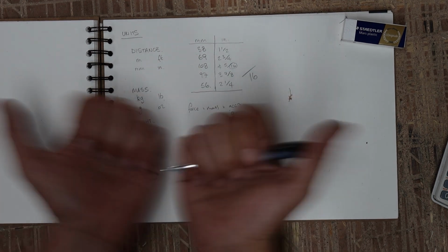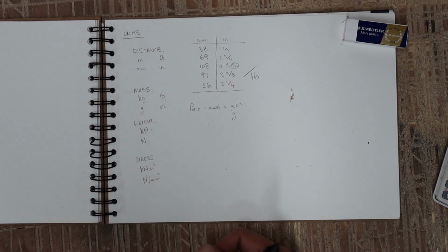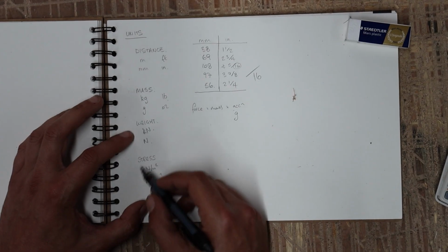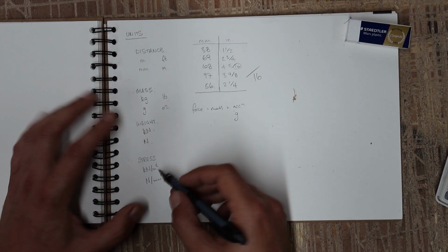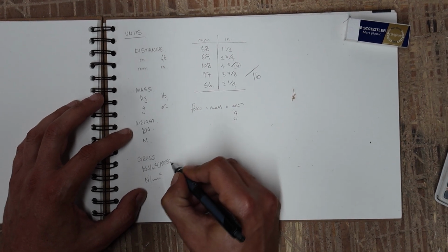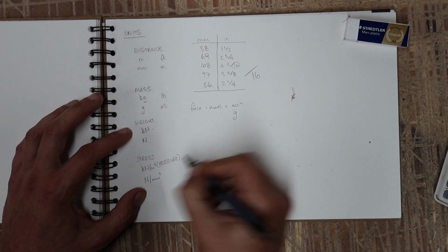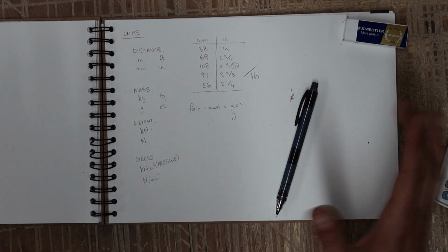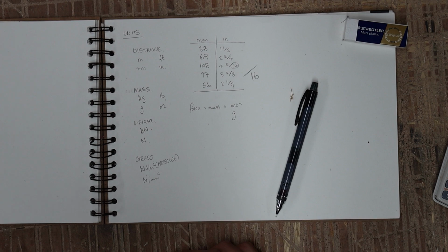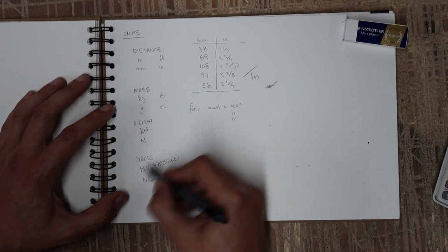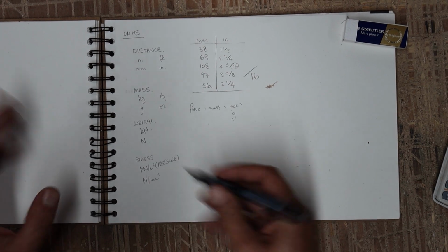That's what I was just doing, force divided by the cross-sectional area of the section we were discussing. And in general terms, we don't generally tend to use this for structures. We generally tend to say that this is a pressure rather than a stress. And the reason is because not many structural members have a cross-sectional area that is in meters squared. It's normally in millimeters squared. So this is more pressure. We generally use stress, newtons per millimeter squared.